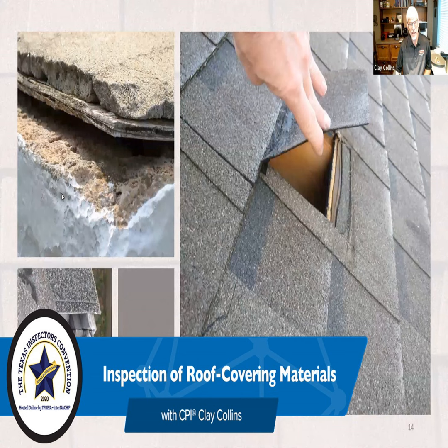So what do you do if you have a problem with that? Well, the manufacturer says that you can just use some adhesive to hand seal those. And in fact, you'll have some manufacturers that say hand sealing is required in certain cold weather or on steep slopes, mansard roofs.